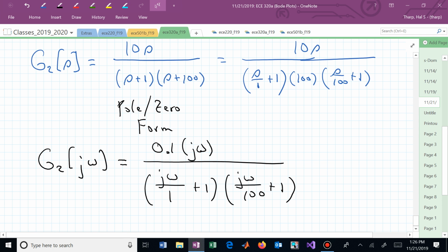The poles and zeros at the origin are always sloping in their magnitude contribution. The breaks, the changes in slopes, are just going to be at 1 and 100. Here we would say, oh, a decade before 1 at 0.1. So anything below 0.1 would be small for this system.